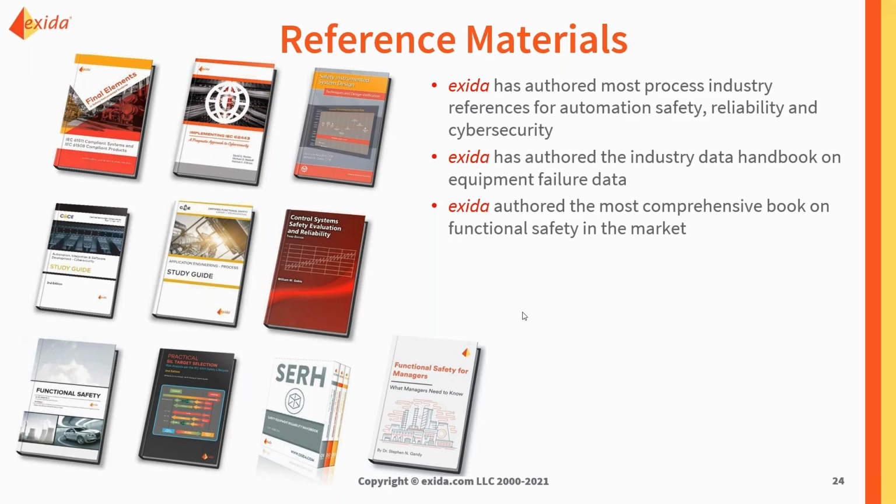The Excellencia suite provides a full lifecycle tool. So once you get the data into any one of these tools, it's available to the rest. And it flows from the hazard and risk assessment all the way through to the data gathering in the field, SIL stack. If we've identified alarms as layers of protection in the PHA or LOPA, those can be brought into the SIL alarm tool, so we can start to create a master alarm database.